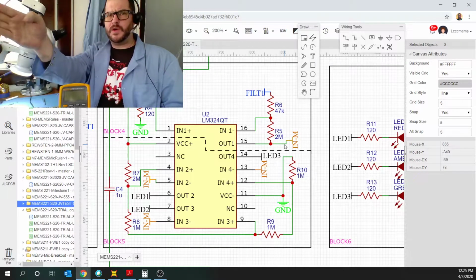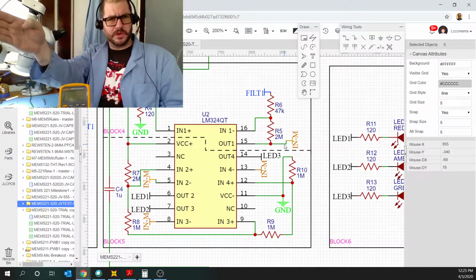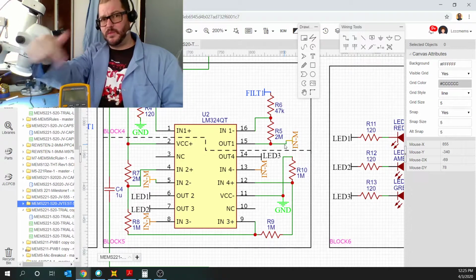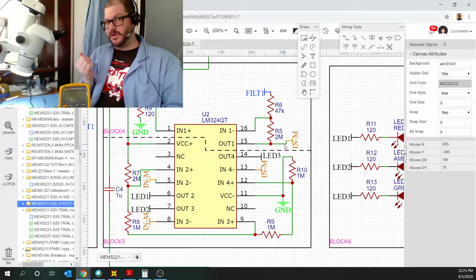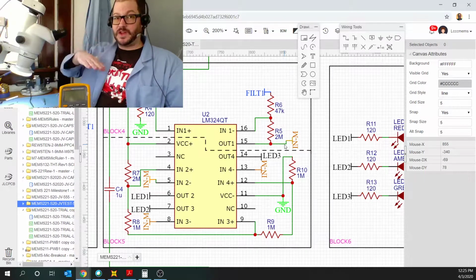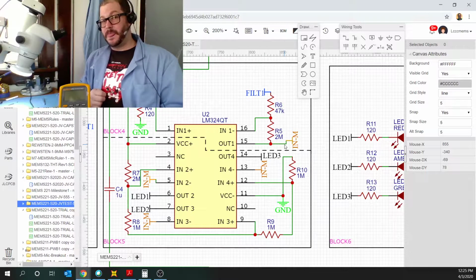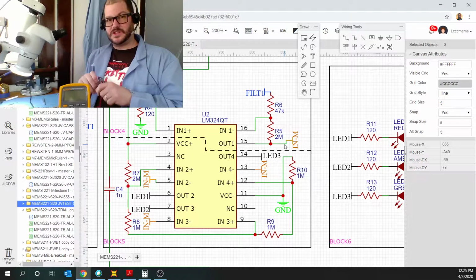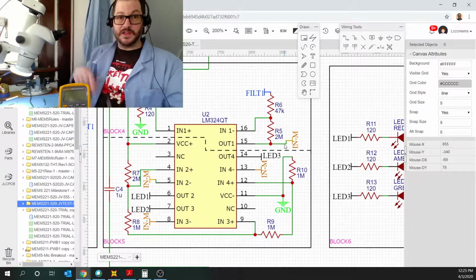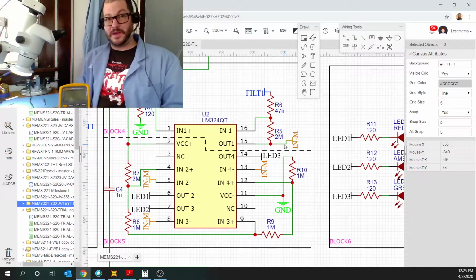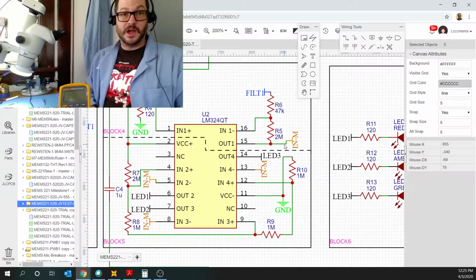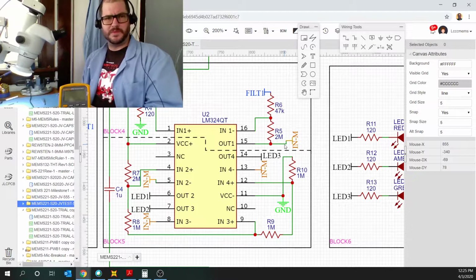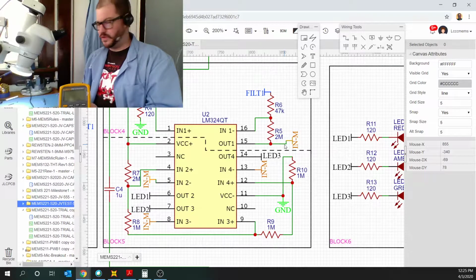When they source power going out, they're only able to output 2.3 volts, and the LEDs need some of that voltage to be able to turn on. So I have configured them inversely so that they are sinking power going into them, effectively using 3 volts down to 0, because when the values of the inverting and non-inverting sides are such that the output is effectively grounded, that means I've got 3 volts down to ground, and that effectively makes my LEDs a little bit brighter. At some point, I'll demonstrate this with a series of circuits where one of them is an output, the other one is an input, and you can see kind of what that is.